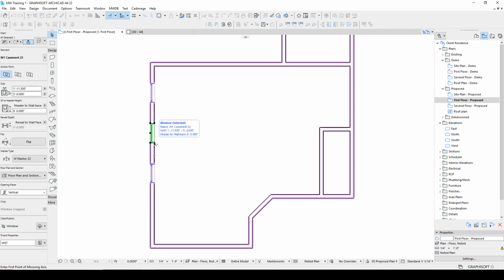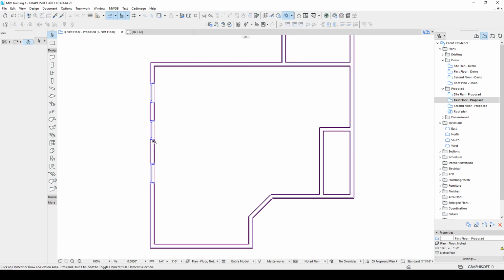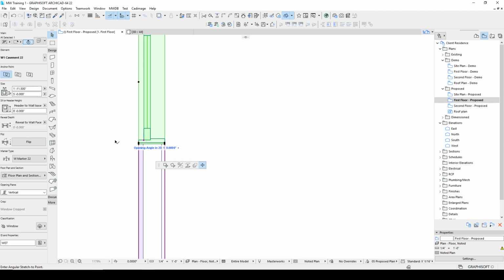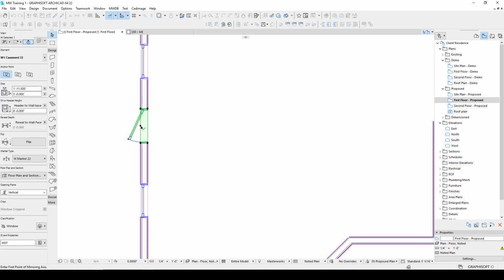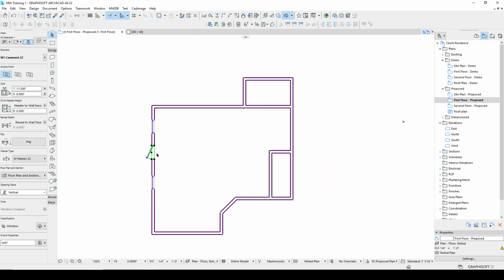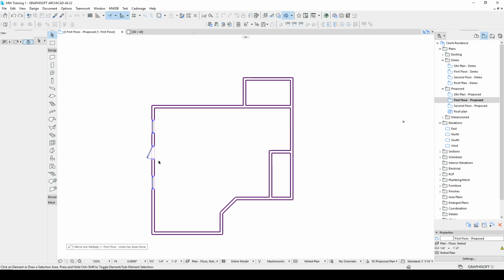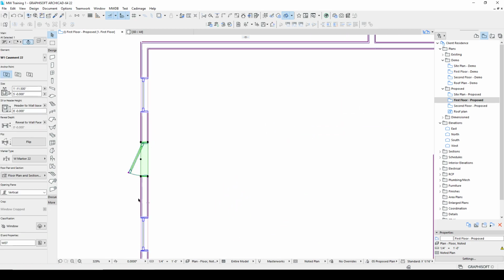If I want to mirror it and just flip it, so in this case I have a casement, so sometimes I might want to mirror it. Hit F7, click, and I'm centering it, rotating it about the center. I can also flip it inside and out. I want to mirror a copy from one side to the other. So all the same tools, nothing terribly surprising there.